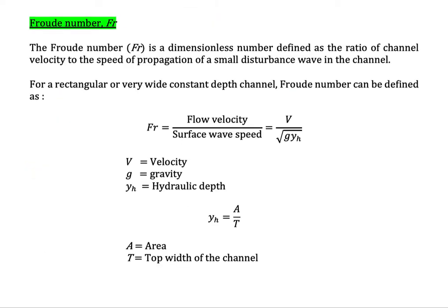So and then I would like to introduce you another dimensionless number that is very important in open channel flow. Okay, in flow in pipe, we always use Reynolds number because we have diameter to calculate. But for open channel flow, we don't have diameter. That's why the Reynolds number is actually only used to determine whether it is laminar or turbulent. So I would like to propose here the Froude number.